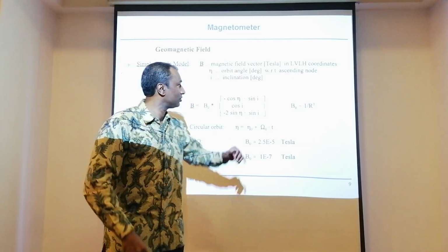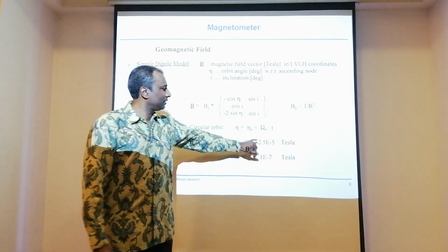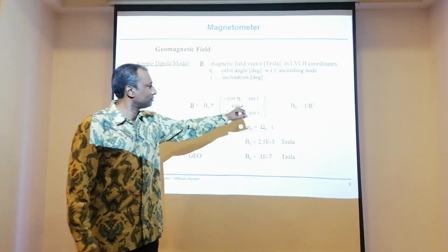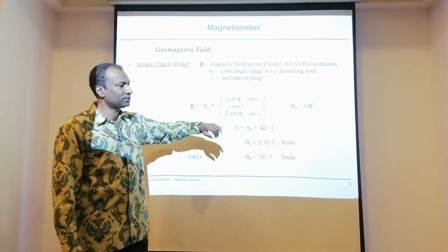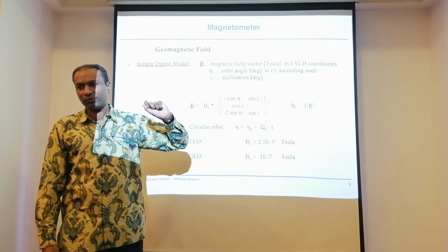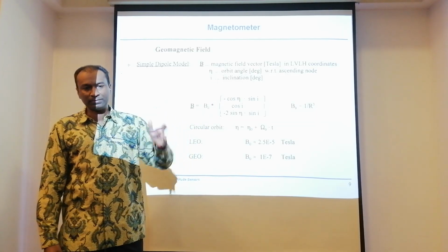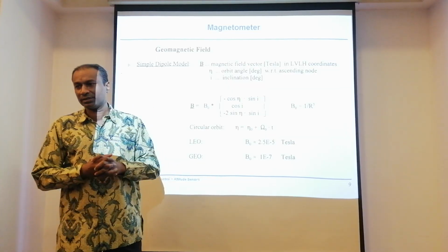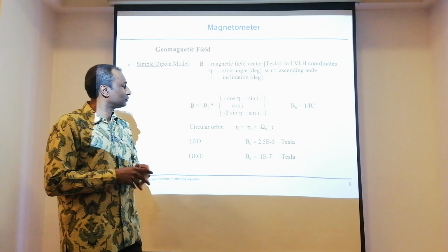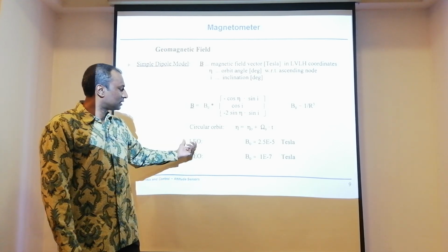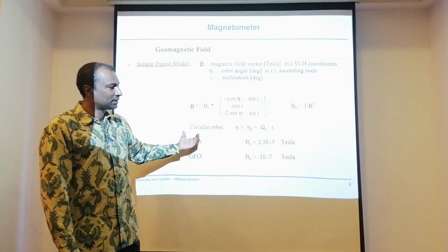So when it's zero, then you will have the orbital frequency only. When you inject the orbital frequency back into this particular equation, this equation will look exactly like how you've been using it for your estimation of disturbances, and of course for your attitude actuator torque, for magnetorquers. So typically you can use it for estimation in a low Earth orbit.